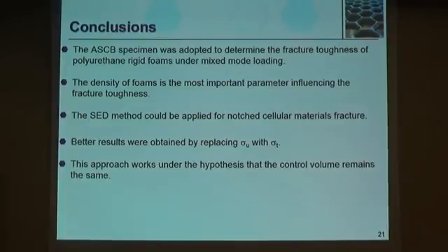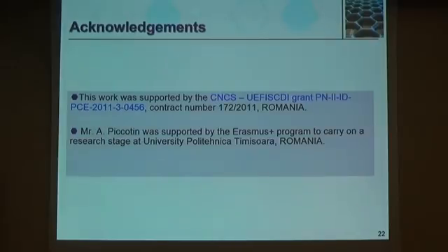This strain energy density criteria could be applied for notched cellular materials to predict the fracture load, and it is better to use the strength obtained on notched specimens than the ultimate tensile strength. Our hypothesis seems to work, in which for mixed mode we maintain the control volume constant and equal to the control volume from mode 1.